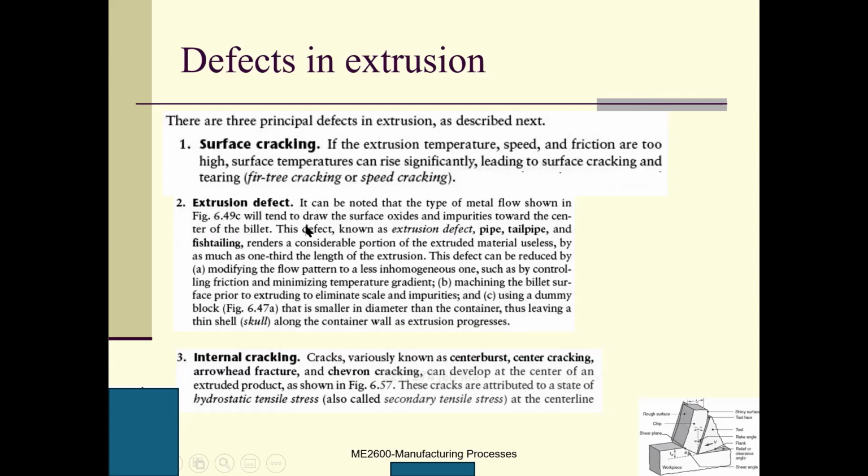So this effect is that surface oxides and other impurities are introduced into the billet. As a result, the material is not as pure as you think. So this might be a defect. It depends on how you are going to use this final product.